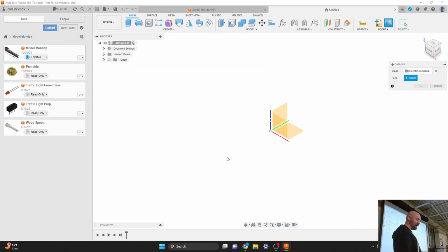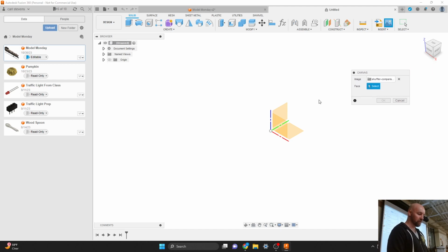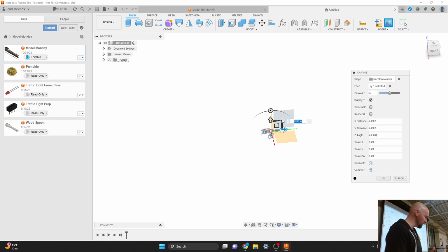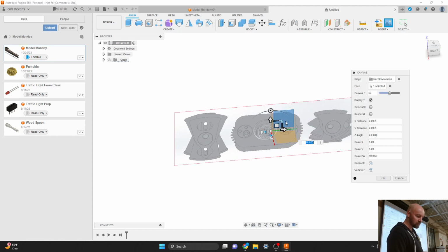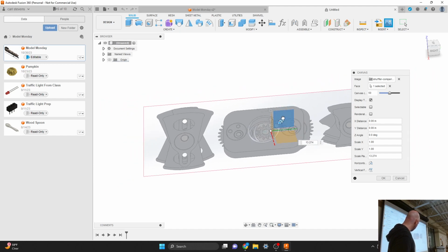Carl. And all I have to do is pick a face on which I can put this image. I'm going to pick the right face. I'm going to draw on the right side because we're drawing the side of this thing. Once you click a face here, you'll see a tiny little image pop up here. We're going to scale this appropriately later, but for now, just drag it a couple of times. You can click on the little widget here, the little curved section in between the two perpendicular lines, and click and drag on it in order to scale it.